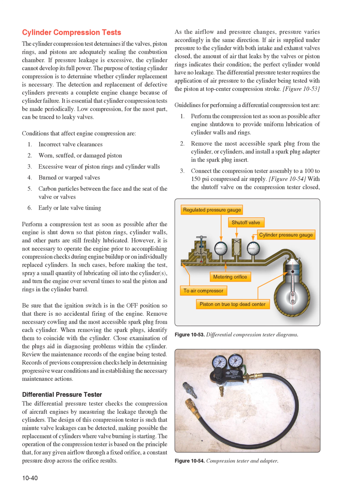Low compression, for the most part, can be traced to leaky valves. Conditions that affect engine compression are 1. Incorrect valve clearances. 2. Worn, scuffed, or damaged pistons. 3. Excessive wear of piston rings and cylinder walls. 4. Burned or warped valves. 5. Carbon particles between the face and the seat of the valve. 6. Early or late valve timing.